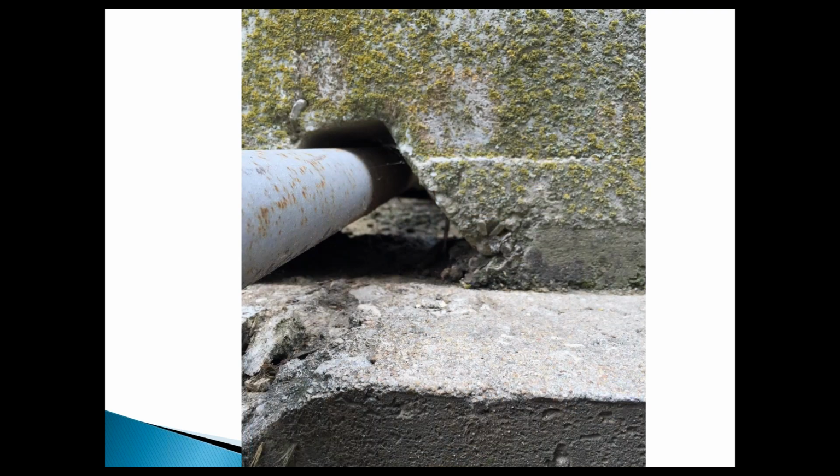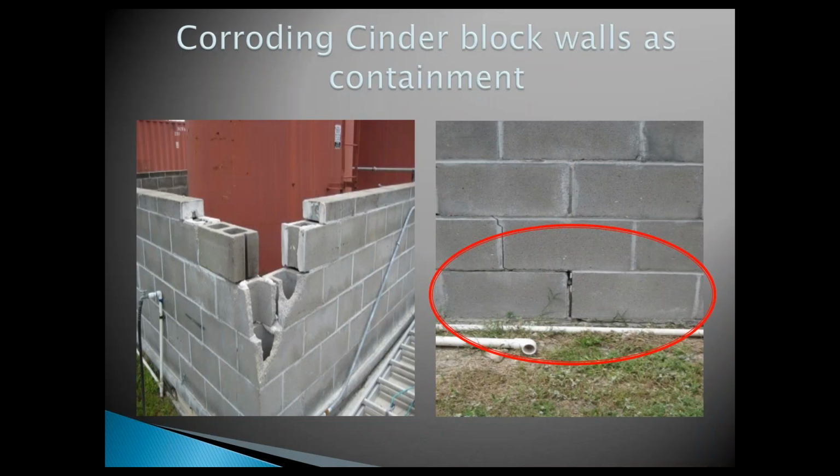Penetrations in a dike wall. Holes in a dike wall mean you no longer have containment up to the point where that hole is. So if it's at the bottom, you have no containment. We see this all the time.